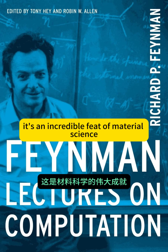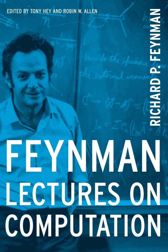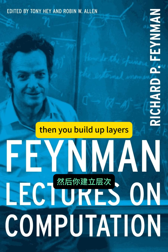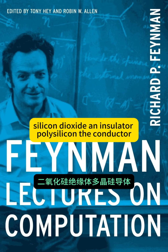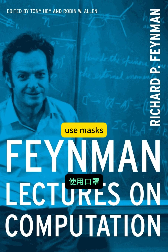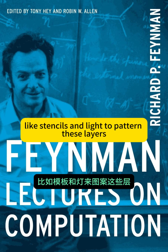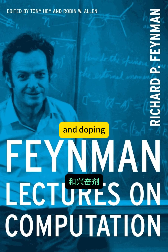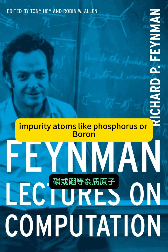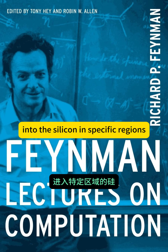It's an incredible feat of material science and engineering. You start with an ultra-pure wafer of silicon. Then you build up layers: silicon dioxide, an insulator; polysilicon, the conductor; metal layers for wiring. You use masks, like stencils and light, to pattern these layers. And doping, adding impurities. Crucial. You selectively introduce tiny amounts of impurity atoms, like phosphorus or boron, into the silicon in specific regions.